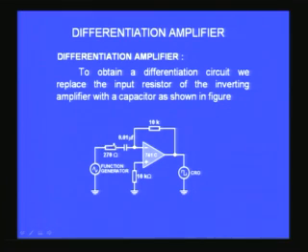So I have used 270 ohms in series with the capacitor, then there is a 10k resistor in the feedback, and I have also used a 10k resistor for the other input for connecting to ground. This 10k I have added for balancing the input bias current differences between the two inputs, about which I will discuss a little more in detail later on.